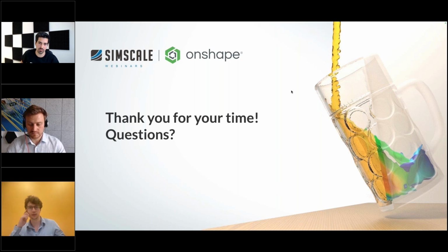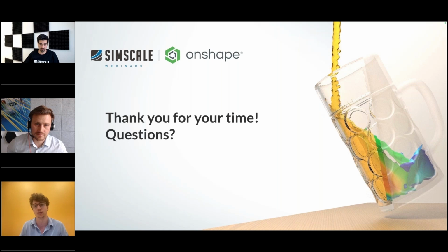So the way in which you're connecting from SimScale to Onshape is through your login, right? So you're going to be able to connect your Onshape account right from your SimScale account. You'll be in SimScale, you'll log into Onshape, and then you'll be able to pull data from your Onshape environment into your SimScale environment. So there's no need to download any sort of parasolids or steps as you might do in a more conventional environment, and then re-upload those.